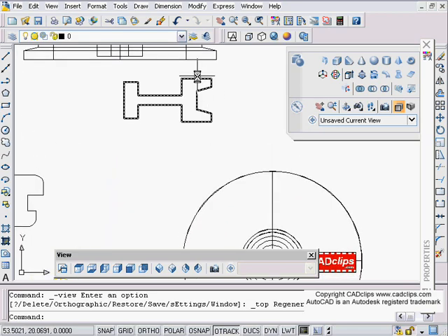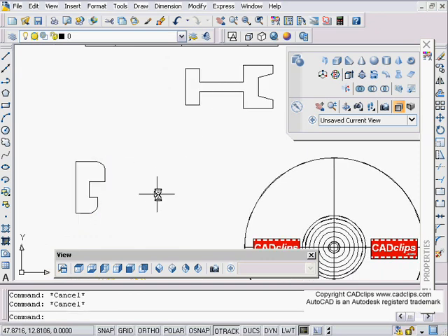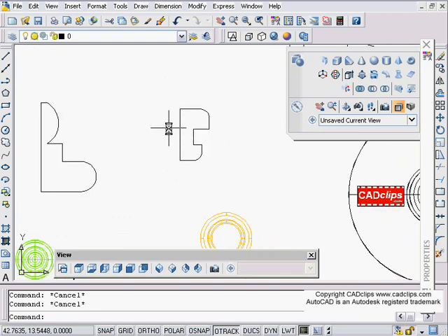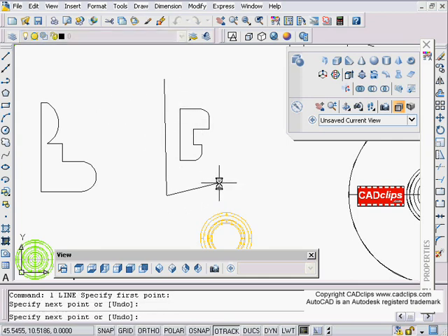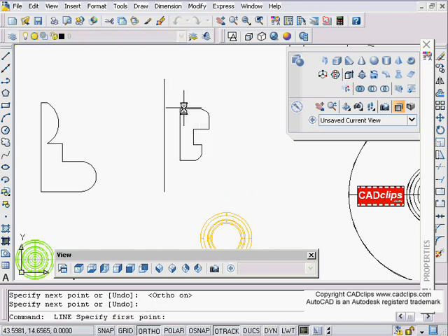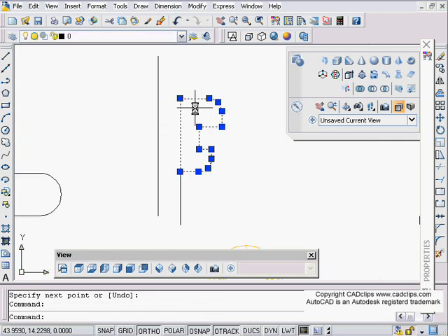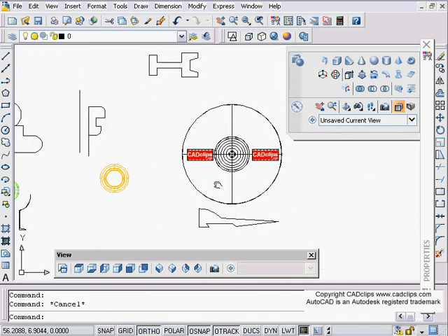There are different things you can do, and basically all you need is some sort of a polyline profile, and then you take that profile and revolve it around an axis. Now the axis needs to be in the correct plane. In other words, if the axis is pointing straight up here, this won't revolve around it. It has to actually revolve around. So for this, I probably want to turn my ortho on here, or I could do it with my snap on. I could have an axis there. Now if I revolve this around here, I'll have a hole in the middle, and if I revolve it around here, it'll end up just being a solid.